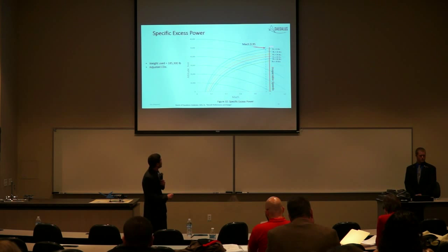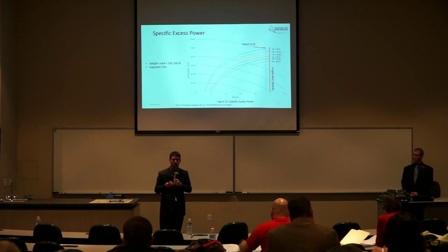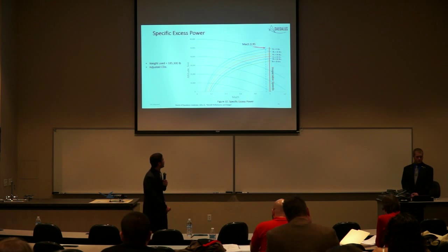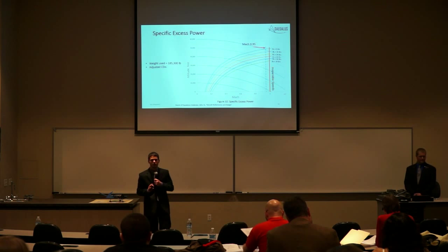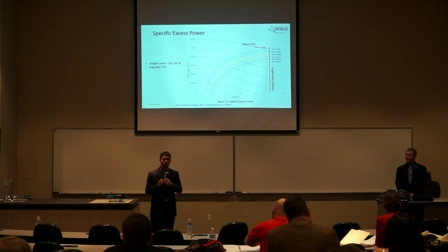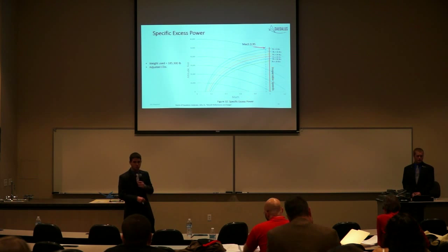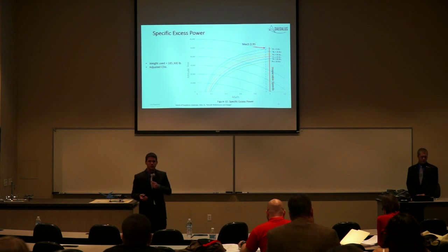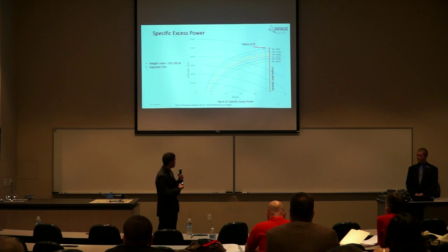So the P sub S of 0 here, this blue line, basically shows at that point we have no excess power, so we can't really change our flight dynamic. We can't go much slower, we can't go much higher. Now, a couple things to note about this. The dashed blue line here is at Mach 0.95. That's the line of its maximum speed. Any faster, the engine will begin to choke due to shock waves. And of course, an absolute maximum speed of Mach 1. And from that point, we can also conclude that our maximum altitude is about 48,000 feet. And that's due to some loss in weight as well with calculated fuel burn.